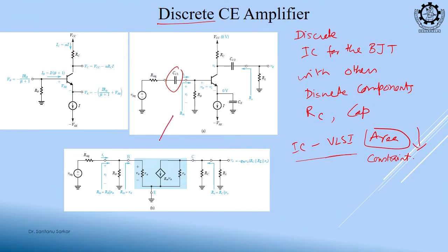Okay. So, this is redrawn here by considering VCC is shorted to ground, all the capacitors are shorted, and this will look like this. Okay, that we have discussed several times. Why are we discussing it several times? So that you get familiar. Okay. And if Early voltage is considered, another extra term will come, that is R naught.